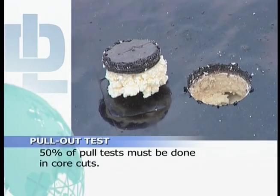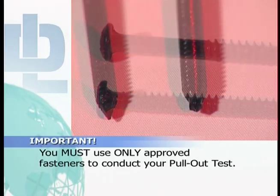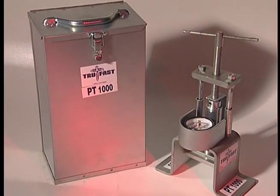50% of your pull tests must be performed in core cuts. To verify a deck's integrity and to establish fastening pattern limits that meet Duro-Last specs, you must perform fastener pull-out tests on the roof deck with approved fasteners. The fastener manufacturer, Duro-Last contractor, or Duro-Last sales representative must conduct this test at the job site. Always have a pull tester and keep it in proper working condition.